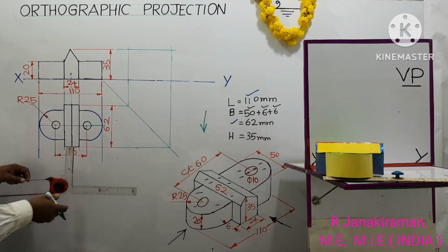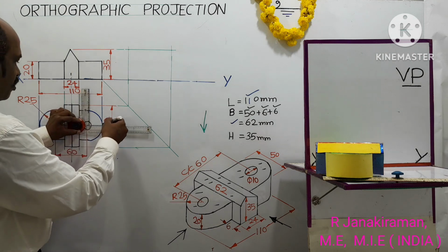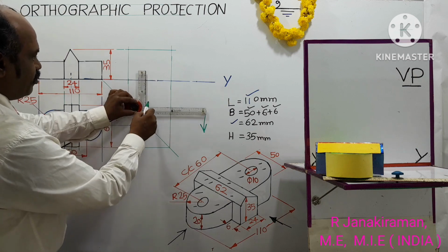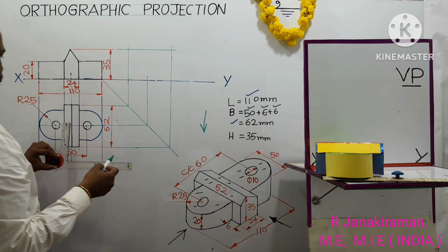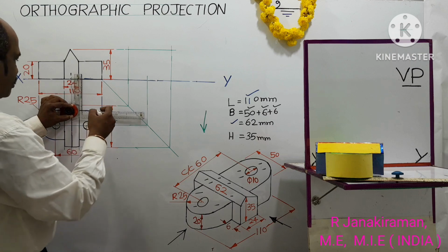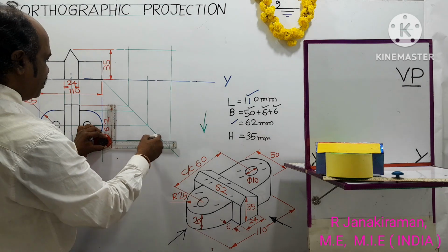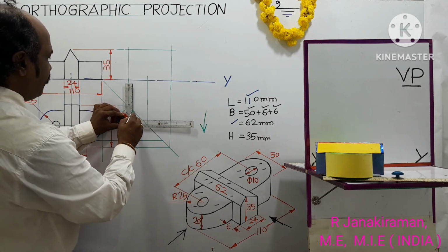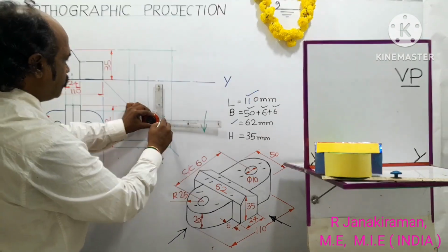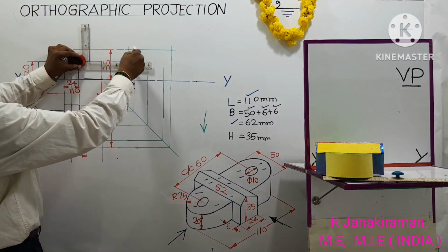Okay. Then other points are also projected from the previous top view. The center line passing through the two small holes is also projected. Draw vertical projectors, one by one you can do it. Then the inner semicircle edges are also projected. Where this projection line intersects with the mitre line, there you draw a vertical projector. So project the base thickness, 20 mm thickness.